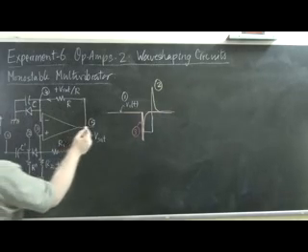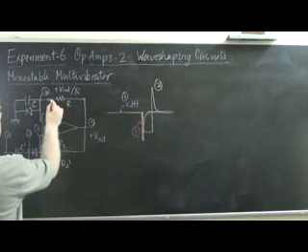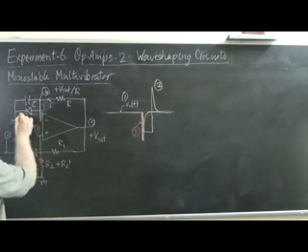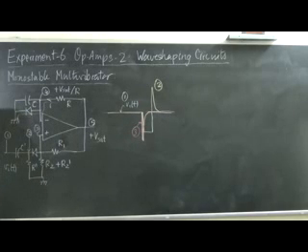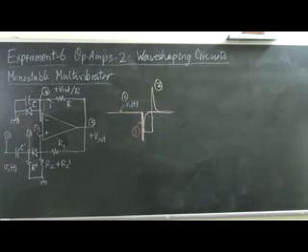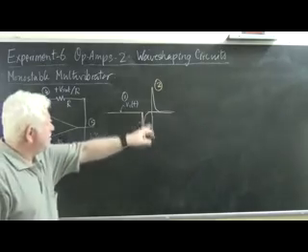So the current I passed through the resistor, through the diode and into the ground this way. And continually until this pulse was applied, this current was passing through the resistor and the diode into the ground. The capacitor voltage was kept practically at 0 or the cut-in voltage, whichever you would prefer. So that is the state of affairs until this pulse got applied.